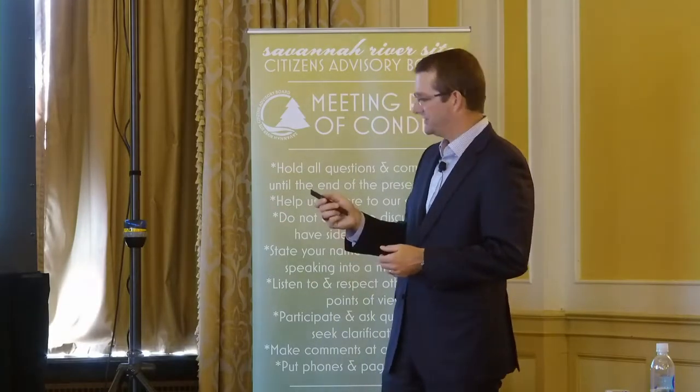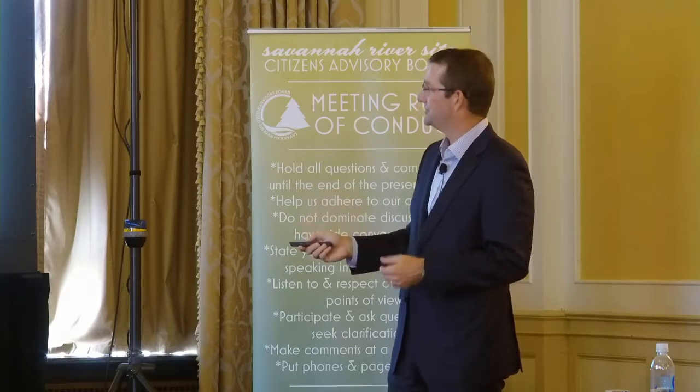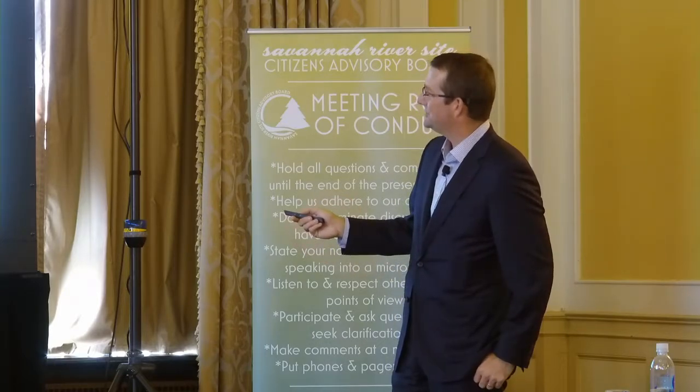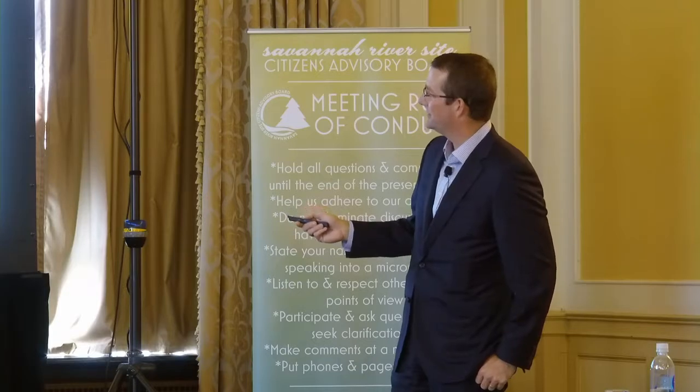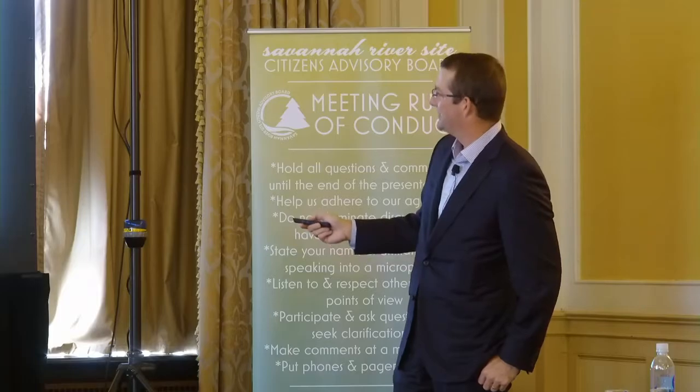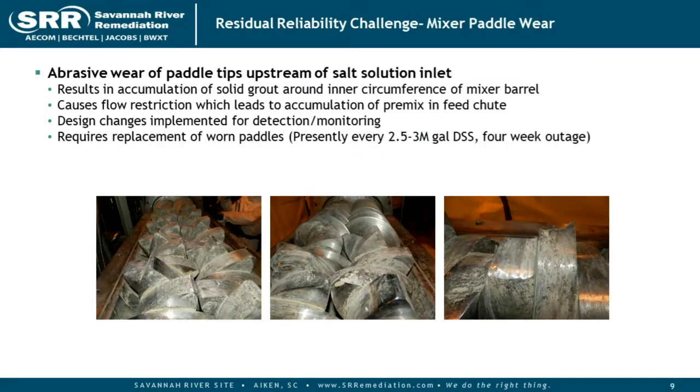And what that results in, and again, I don't know how well these pictures show up, but these paddles here look great. They have nice, sharp tips on them. You're not worried about them in the least. You can see how straight those lines are. As we come over here, this is more towards the back, you can see some shiny areas where they've been worn a little bit. And then particularly, this one has a very good profile. You can see how much mass loss has occurred on that paddle right there.